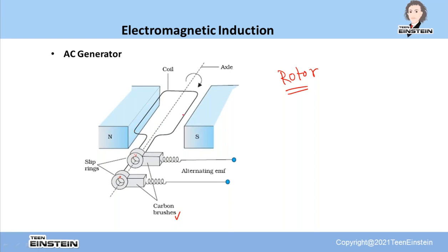So you can just see this is a rectangular coil. Actually, no current will be passed in this coil, it will only be rotated. So this is the rotor with which it is connected. A rotor is a machine which can rotate this coil, and you can see this coil is placed inside a strong magnetic field. These are the pole pieces of an electromagnet, so this is the north pole and south pole. If I draw the magnetic field lines, something like this.